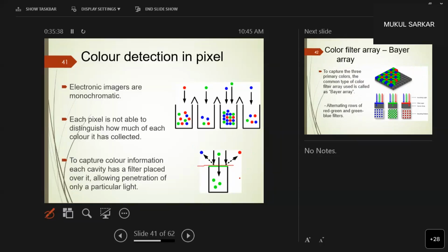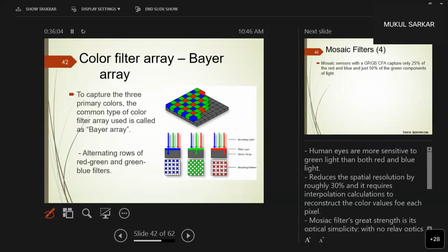So this primarily tells me that color imaging is bad in low light environments, because in color imaging, 2/3 of the photons are lost. Therefore, often the cameras that are made for low light imaging are monochrome in nature, because in a low light environment you have very few photons, and you want to capture all the photons available. You don't want to lose 2/3 of the photons because of the color filter present.